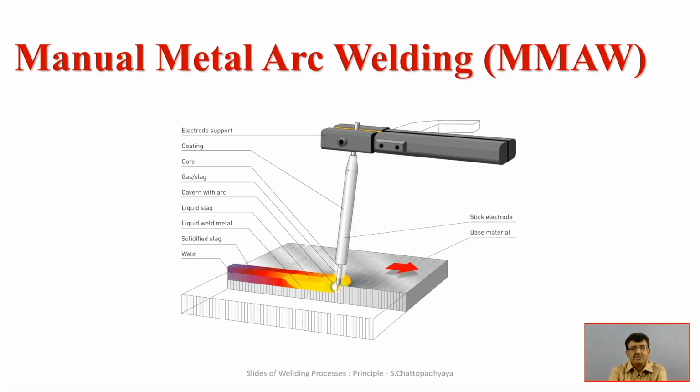metal arc welding process. But one part is that the top part is the naked one, which is gripped, because in order to complete the circuitry, if it is coated by different kinds of oxides, the problem is that they are insulating material. So the tip has to be kept naked without the coating in order to ensure completion of the circuit, and that way it is implemented in the coating of those electrodes. It is one of the most primitive arc welding processes.